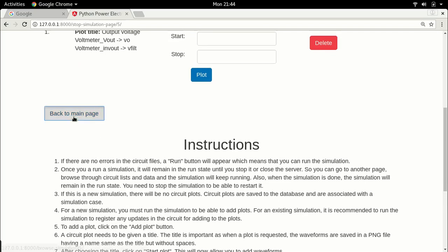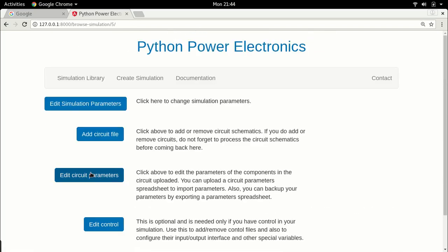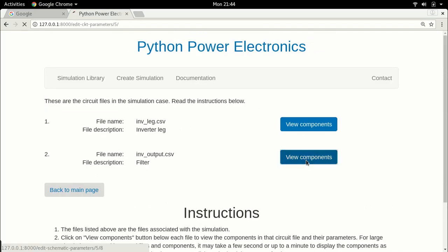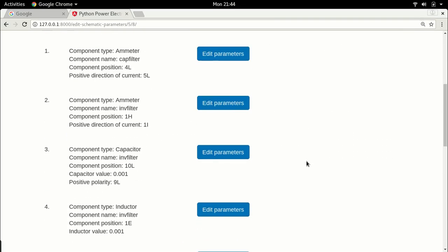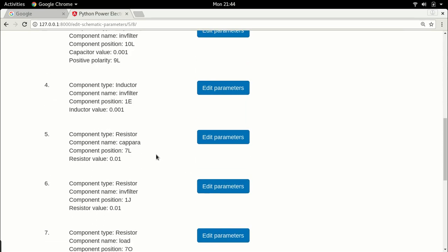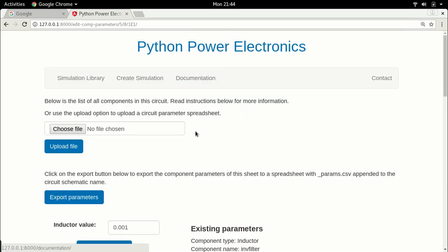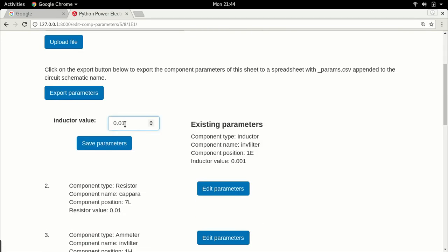Now I'm going to show you that this entire concept is not enough, but I'm just going through this process to tell you how pulse width modulation is better. So now that we've increased the capacitor by 10, let's increase the inductor also by a factor of 10. A 10 millihenry inductor. You want to add a 10 millihenry inductor to any power converter, good luck. This is a huge inductor, huge.